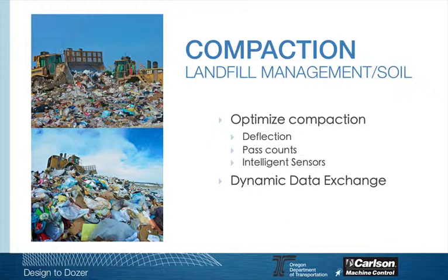But with dynamic data exchange requiring a wireless infrastructure, mesh radios for example, then this data is immediately updated in compactor B, so that if they approach exactly the same area, they will have an up-to-date pass count so that the 2 machines can productively work in tandem.